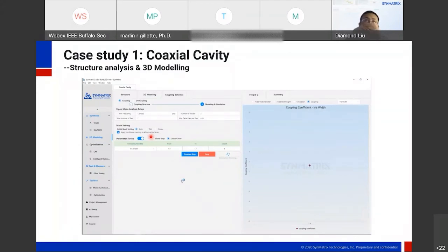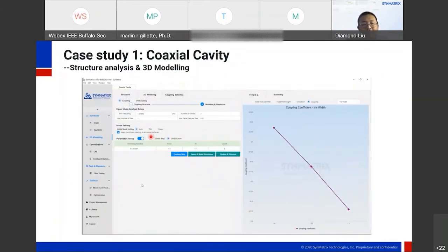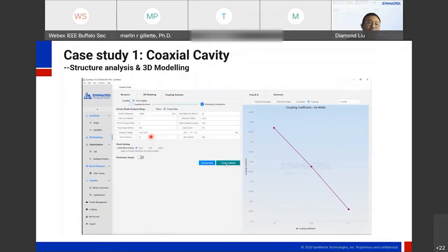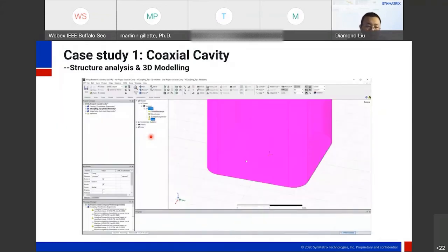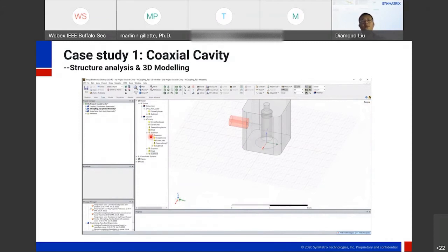That means that the coupling coefficient coming from the HFSS needs to meet my design coupling matrix goal. Okay, it's pretty quick to finish this one. And then I will do the input structures and study there. Same as before. So this result will be reflected as group delay to detect whether I can get the proper input and output coupling there.